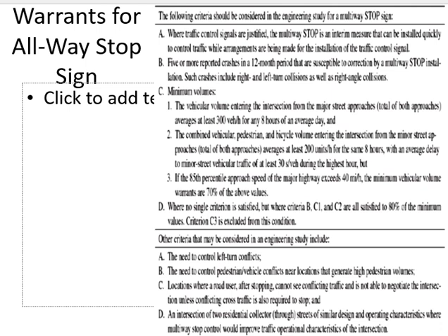Clear? If on the major road it is happening 12 to 8, but on the minor road it is happening 2 to 10, this is not satisfying. It should be in the same 8 hours. Clear? And the last condition is again something which you will see in signal warrants as well. If the 85th percentile speed of the major highway is more than 40 miles per hour, then these values will reduce by 70%.